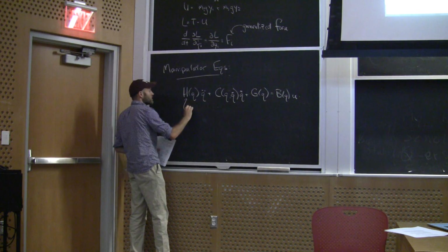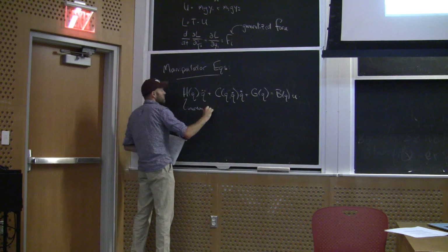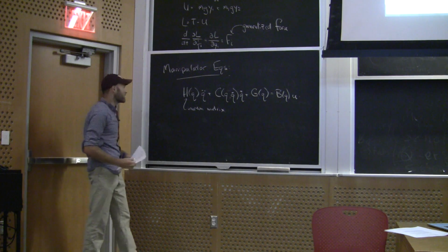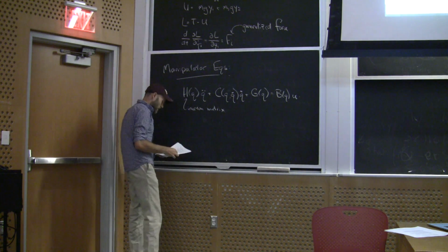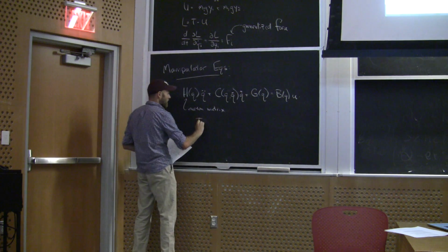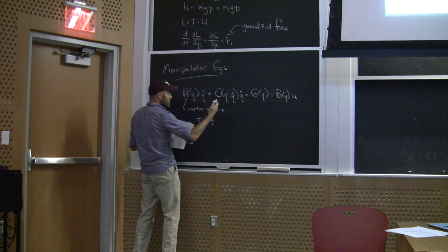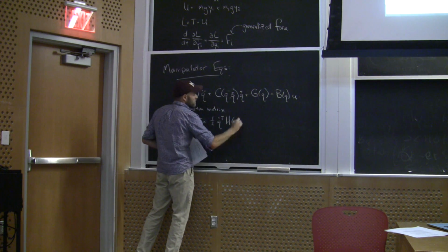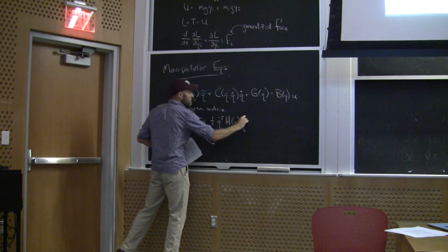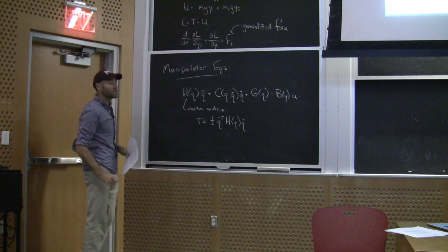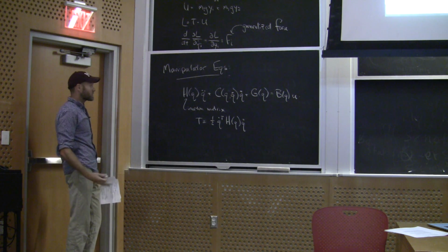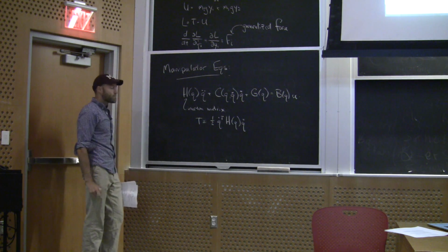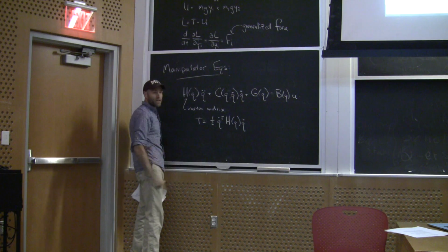This thing is called the inertial matrix. It has properties that we're going to exploit a lot. It's clearly related to the energy. I could have written a sort of generalization of the mass. It's the mass matrix, okay? I could have written it as q dot transpose H q dot. It's just like the role the mass plays in that equation, now in the vector-matrix generalized version of it. It depends only on q. It doesn't depend on q dot.